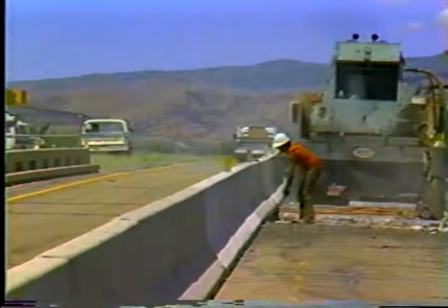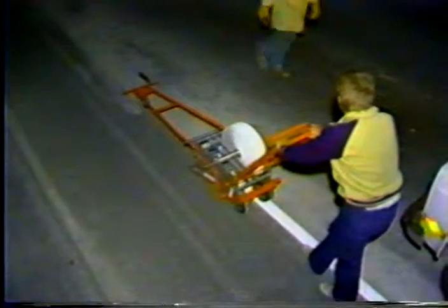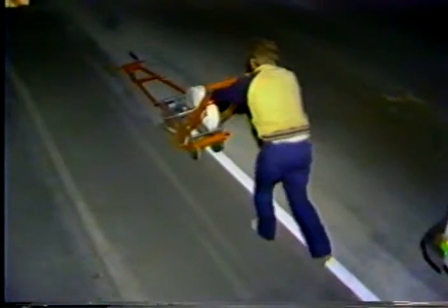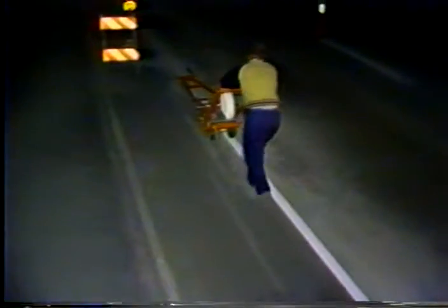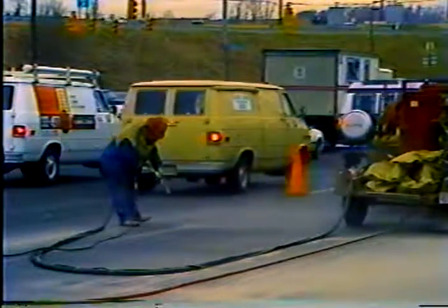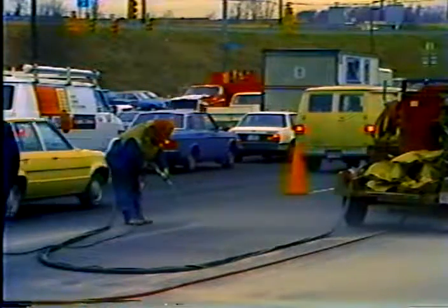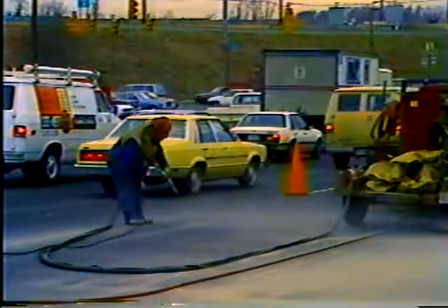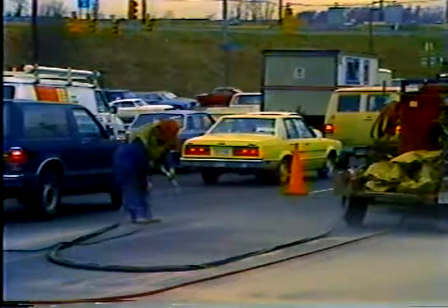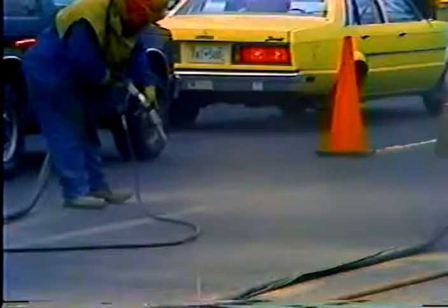better choice of device. You also should check the placement of temporary pavement markings. As with all devices, pavement markings must be the type specified and placed in the proper locations. When work zone markings will conflict with existing markings, the contractor may be required to remove the old lines by sandblasting or another approved method. Blacking out the old markings by painting them over is generally not allowed.